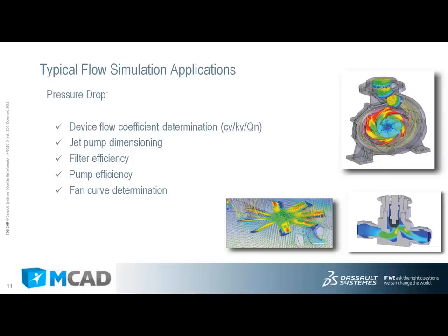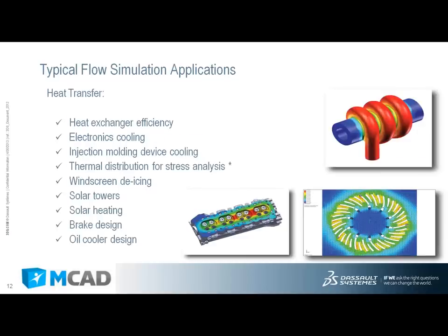So some of the typical applications for Flow Simulation, I'll give you a few of those. First of all, we can look at pressure drop across devices, things like pumps and fans. This allows us to get the most efficient design in our pump assemblies or fan assemblies. So pressure drop is one application for it.